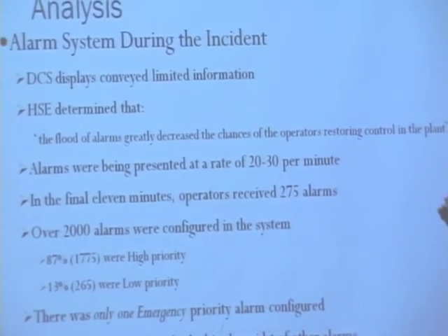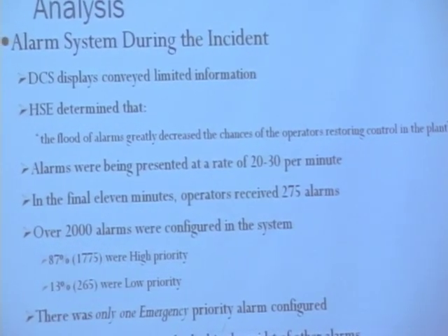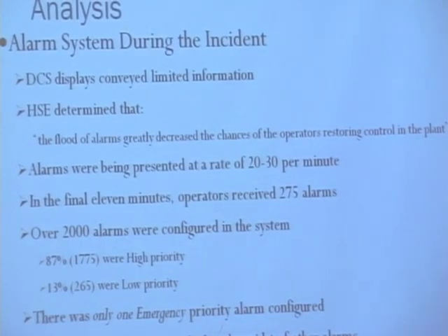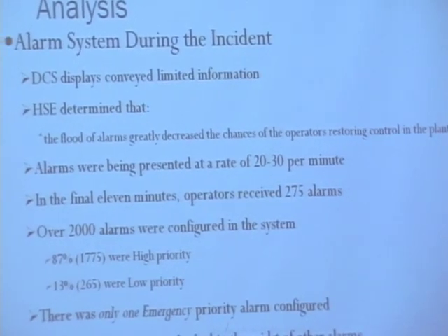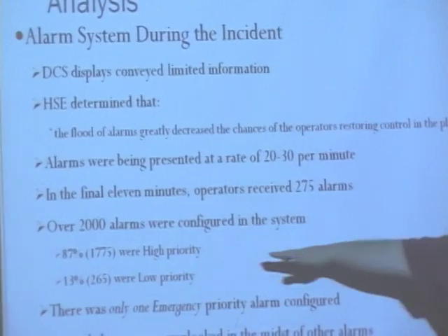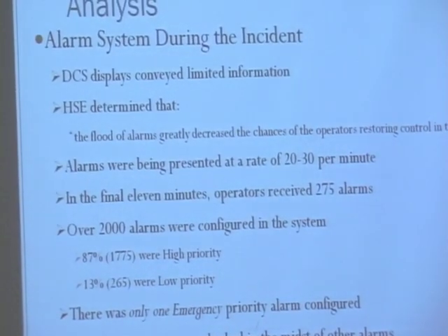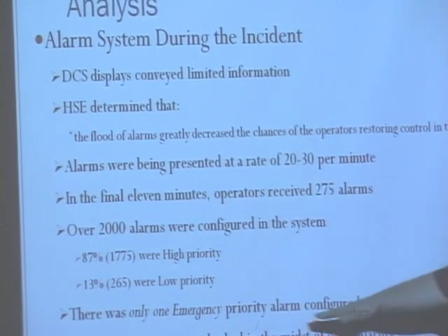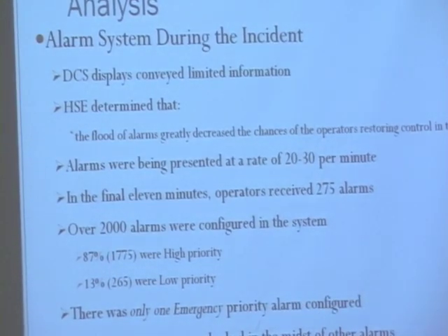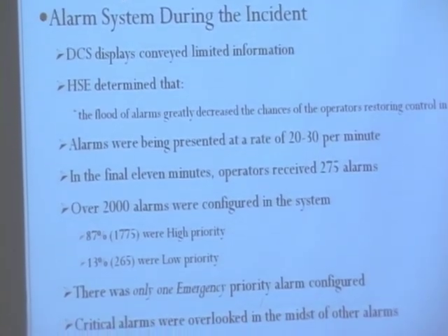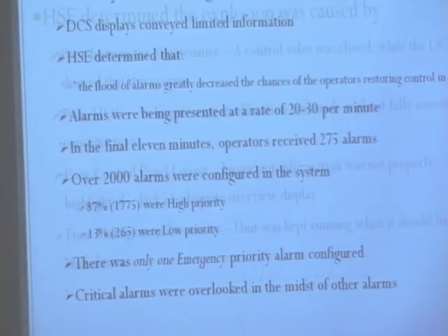Alarms were being presented at 20 to 30 per minute. In the final 11 minutes, the operator received 275 alarms. Over 2,000 alarms were configured. 87% of them were configured high priority. There was only one emergency priority alarm configured in the system, and critical alarms were overlooked in the midst of all of the other alarms.